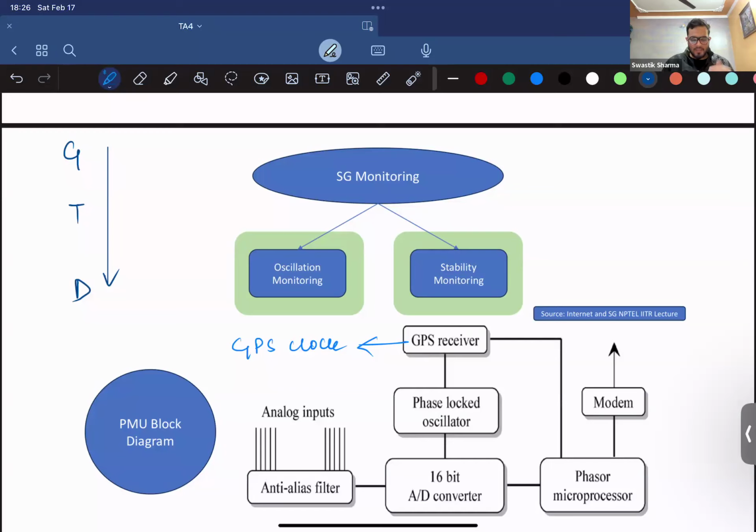The generating side had the generators which sent power down the transmission lines to the distribution side. But now a reverse power flow phenomenon is being seen, because distribution systems are becoming more active because of widely connected DERs.